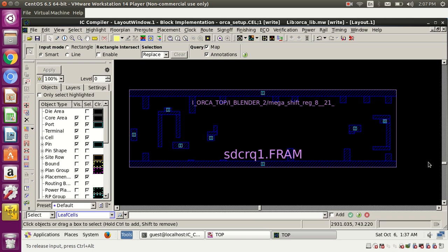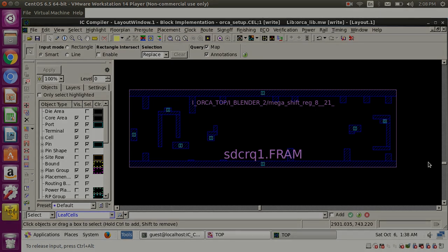So when the clock came, I'll explain in numbers only. This clock and this data both arrive at 1 ps. But to activate the clock, it has to go through the poly and OD, then the NMOS and PMOS transistors should turn on, and only then will the D pin input be transferred to the output. I think you are following me.